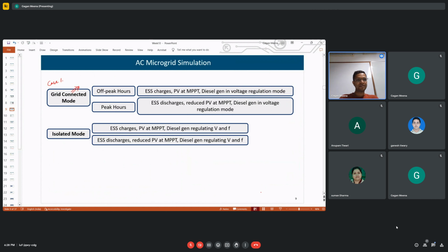Positive sequence is also there, negative sequence is also there. One is trying to move it in one direction, the other is trying to rotate it in another direction. And it is not that the negative sequence is always the same. Unbalance is changing, so this stress also has oscillation. That is correct. The oscillation is not always constant.